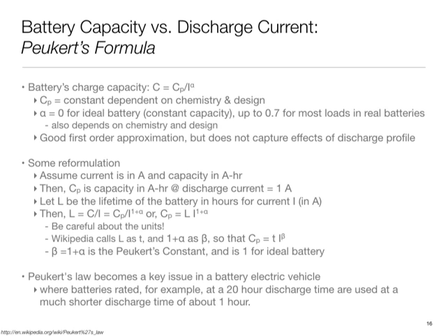And it's a good first order model. It's better than the constant one, but it does not capture your relaxation kind of effects, and it doesn't model the discharge effect that accurately, but it's a very common model which you would see. It's called Peukert's formula, and there are many other variants of it. What I've seen is that alpha typically has a value somewhere in the vicinity of 1. There are many different ways this is presented, so this is one of the ways you would see Peukert's formula.